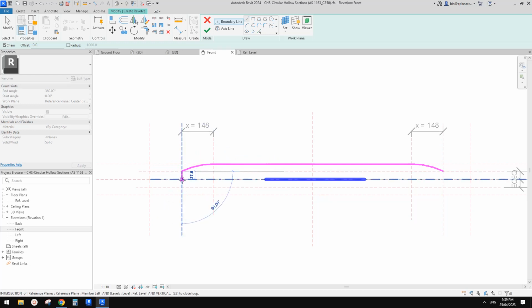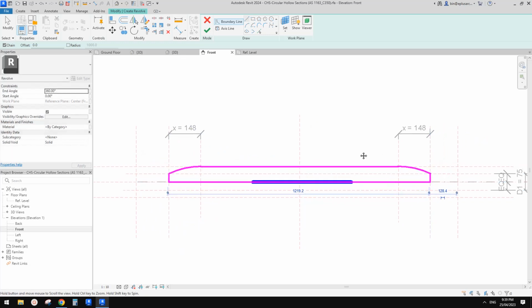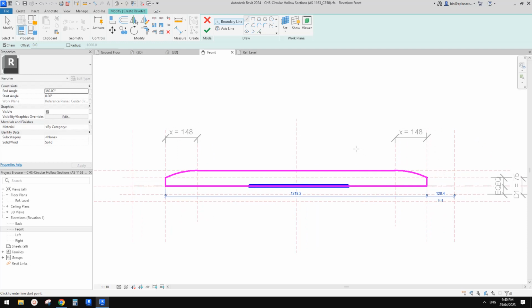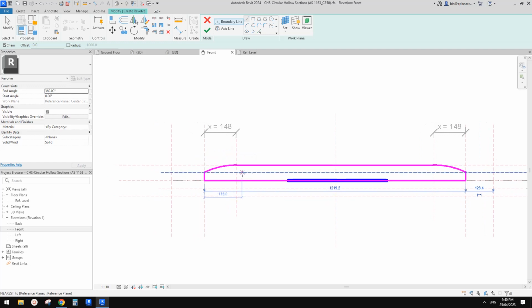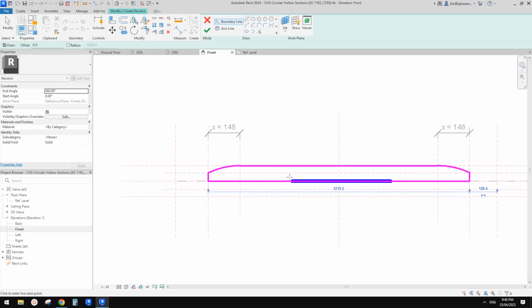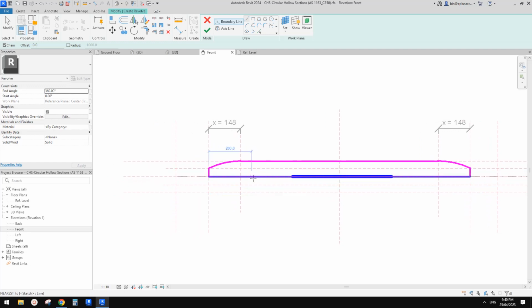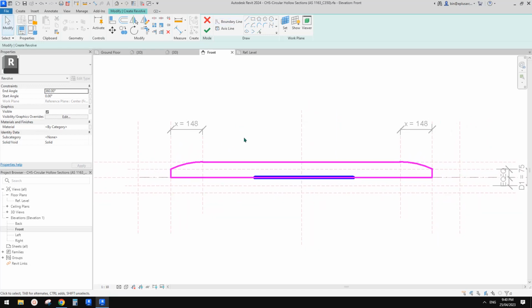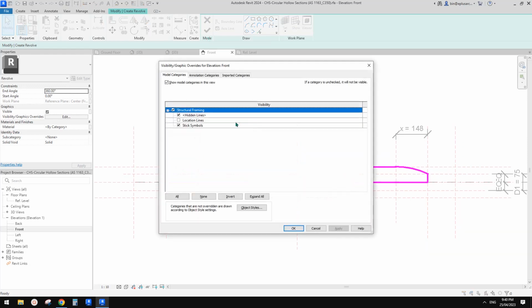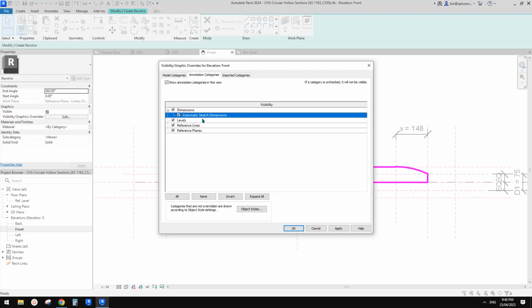Okay, but for this exercise, I'm going to just make it solid, because it can be quite time consuming to try to make all the constraints work, trying to add a thickness parameter. To make it easier, just make it solid. And also before we tick this, let's type VV. We need to check this automatic sketch dimension.